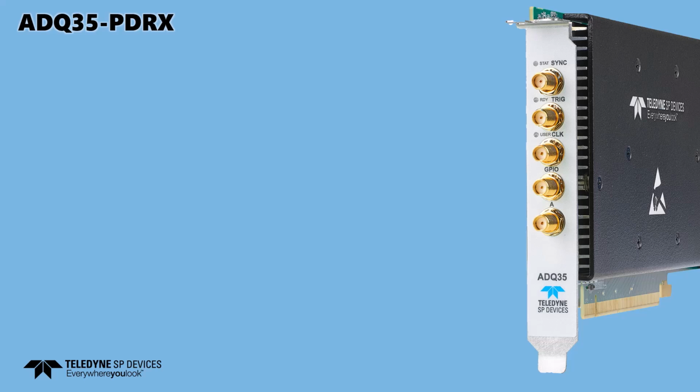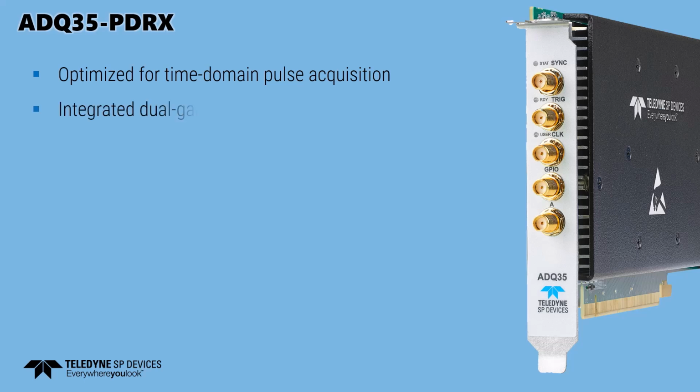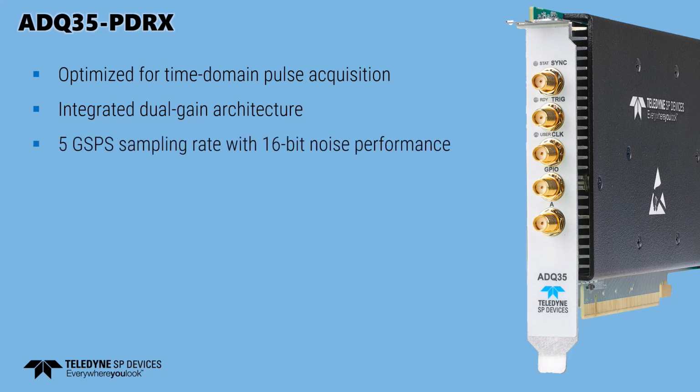That's why we designed the ADQ35 PDRX digitizer. This device is optimized for time domain pulse acquisition. It uses an integrated so-called dual gain architecture in order to achieve 5 gigasample per second sampling rate with 16-bit noise performance. That's 5 times higher sampling rate than the ADCs on the previous slide.